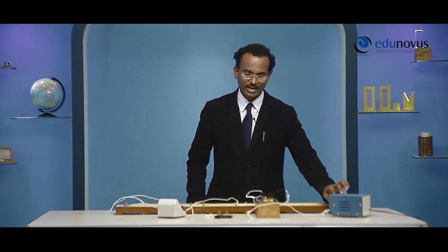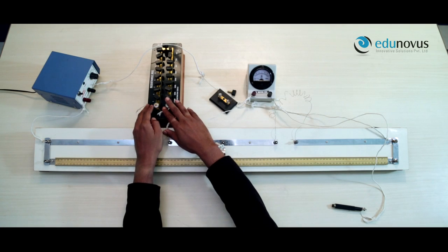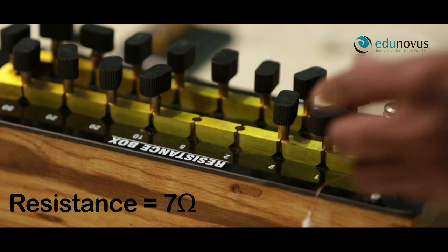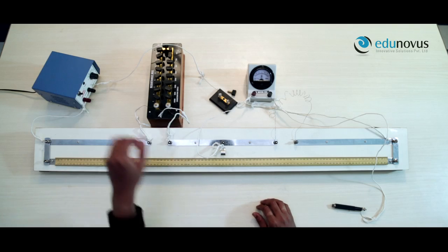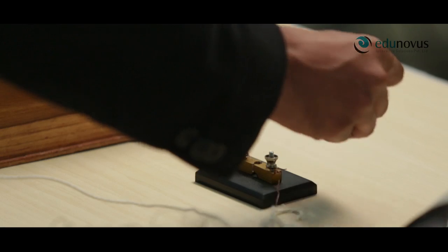Before I switch on the battery eliminator, I should include some resistance in the resistance box. So let me include 7 ohm resistance. I do that by pulling out the plug from 5 and 2 in the resistance box. Next, I will switch it on. Now to close the circuit, I will plug in the key.